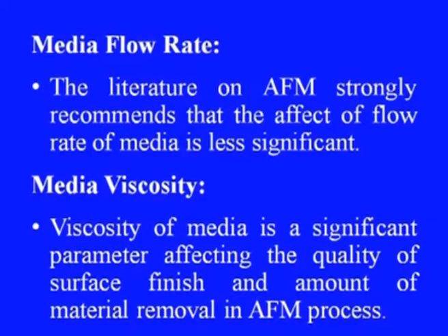Media flow rate. Literature on abrasive flow machining strongly recommends that the effect of flow rate of media is less significant. Then as far as the media viscosity is concerned, viscosity is a significant parameter affecting the quality of surface finish and amount of material removal in abrasive flow machining process. Media viscosity is affected by the type of abrasives, its concentration and size of grains. It is also strongly affected by the working temperature.